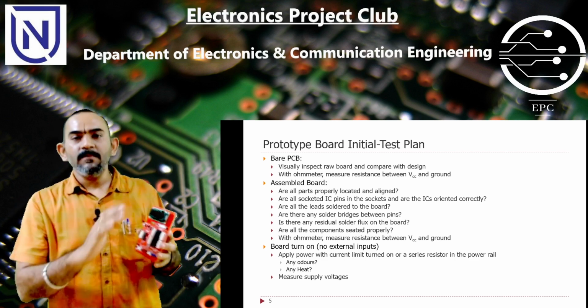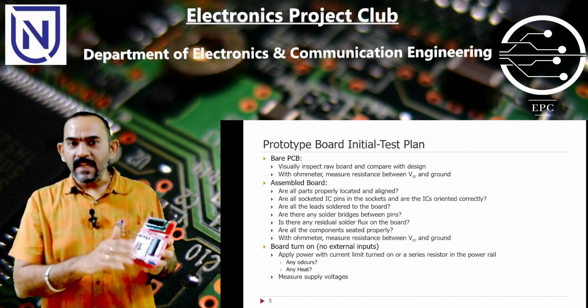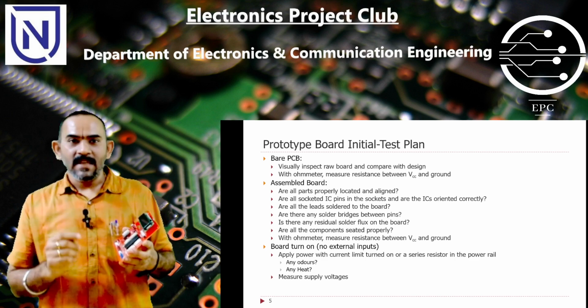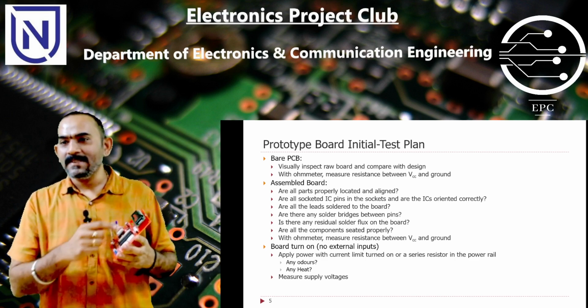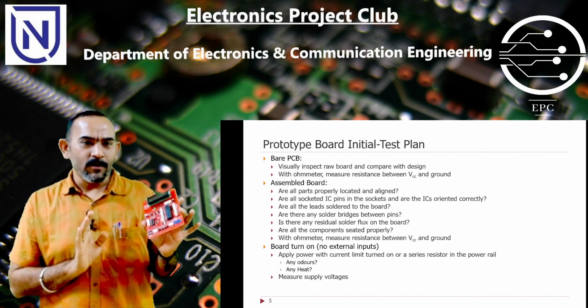Now assume it didn't take extra current, but you keep it running for say 5 or 10 minutes. You also have to have a sharp nose. If there is any smell indicating some burning, that is a clear indication there is some problem in the board.